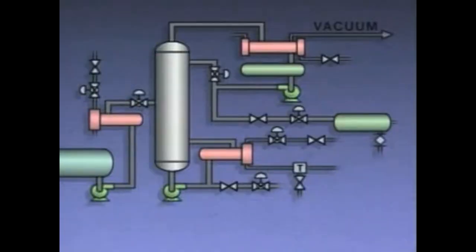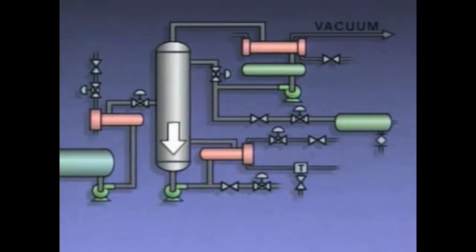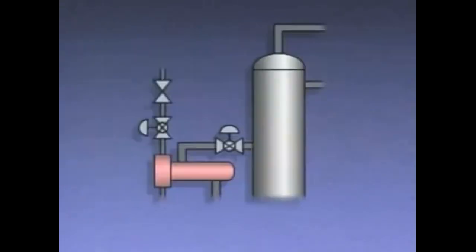the distillation process. In this system, the first thing that's done is to start the reboiler circulating pump. Starting the reboiler pump moves mixture from the bottom of the column, through the reboiler, and back into the column. Filling the reboiler with circulating mixture prevents it from being damaged when heat is applied. When the level in the column drops, the outside operator starts the feed pump. The feed control valve can then be opened as needed to feed the column.